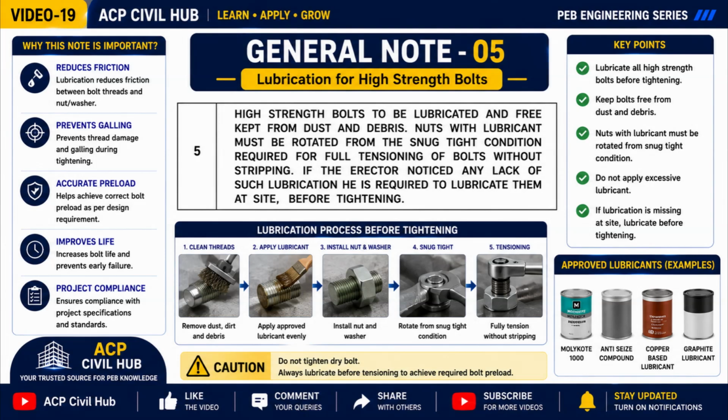Proper lubrication reduces friction between the bolt threads and the nut, allowing the required preload to develop accurately. It also prevents thread damage, ensures uniform tightening, and improves the long-term performance of the steel connection.